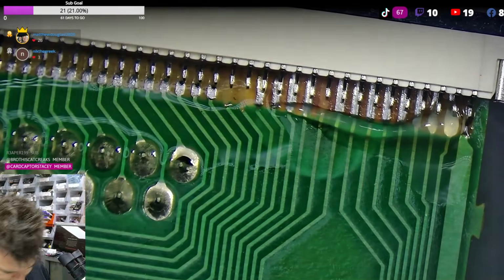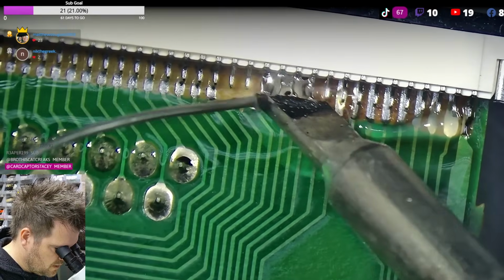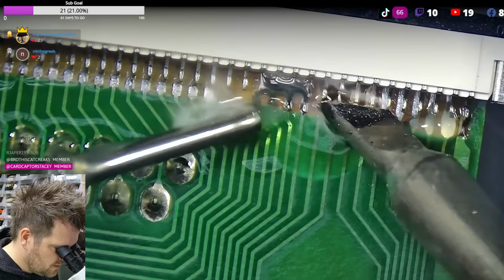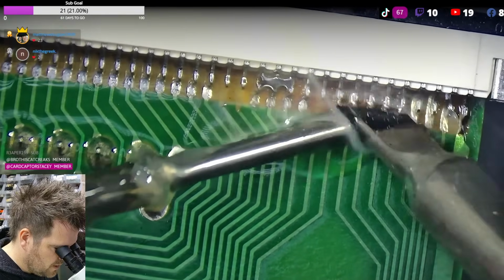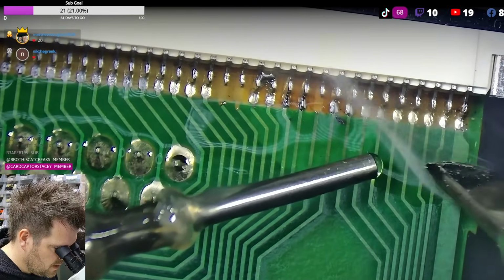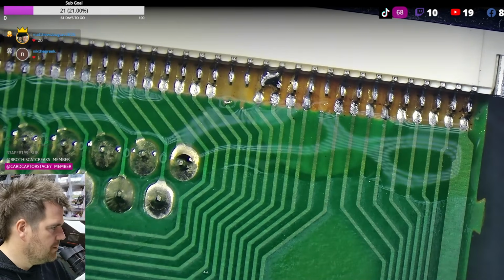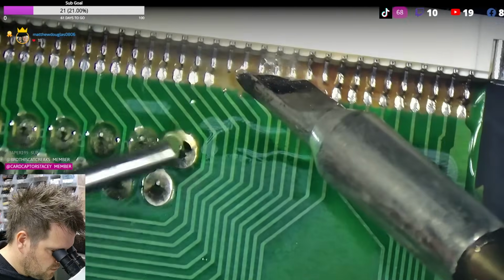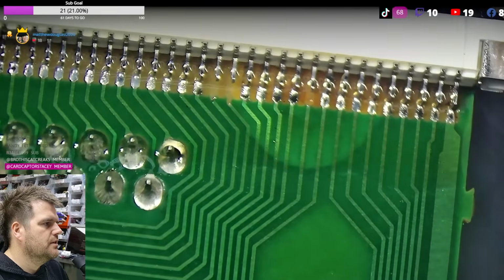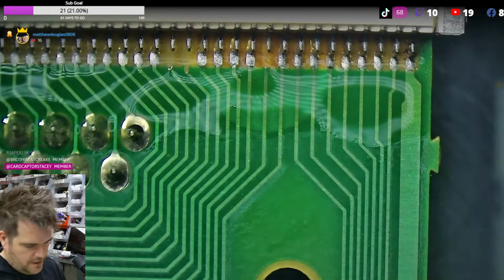And just, as I say, go down with a big blob of solder and just bounce down. At the start, you'll probably find it dries out quick, and that's where you get your extra flux at the very start. And if you've got simply too much solder, you won't get it off the pins, so you can just ignore the start, for example, here, and then once you've done, clean your iron tip so there's no excess solder, flux back in with a dry iron, and it comes off. So just practice basically, and you can get it so that all these are fine.